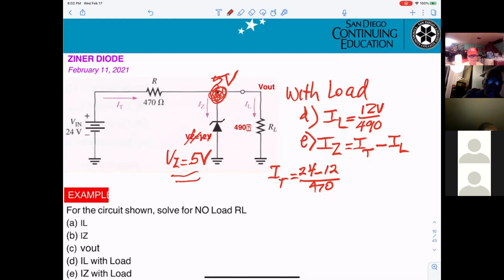What happens if the input voltage is 6 and the Zener diode is 5? Yeah, it's still breakdown, it might be higher than 5 though. Theoretically that's what's supposed to happen, but I tried that on Multi-Sim 7 and it went 2 volts over before it actually broke down. Yeah, maybe you can keep that in mind when you go into the simulation.